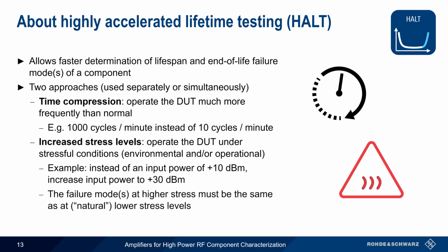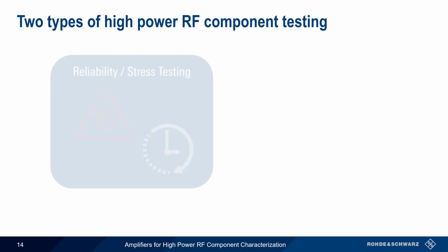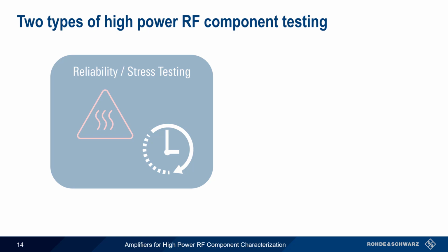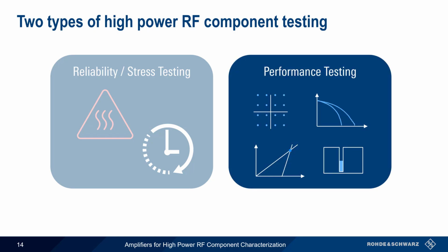Note that in order to provide valid results, the failure mode or modes at these higher stress levels must be the same as, or at least very similar to, those that would occur under more natural, lower stress levels. Now that we've covered reliability or stress testing, let's move on to discussing performance testing of high-power RF components.